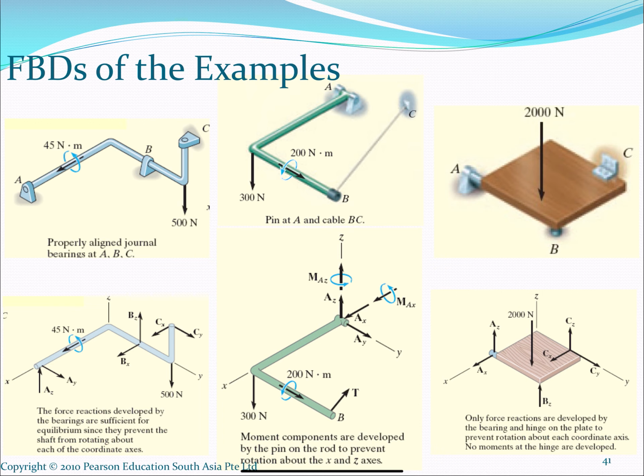When we take external equilibrium, we don't really know what sort of internal forces develop in the members. And these internal forces are really important in order to design these elements. If you have a lot of tension inside your rigid body, you have to provide a good material that is able to resist tension, of a certain shape and certain dimensions.